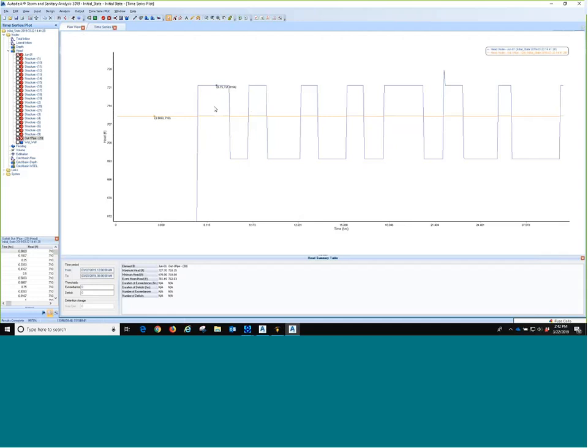So I'm going to use this information and say, hey, just so the thing dribbles out of the end, I need that many feet of head for my pump, and I can use this actually as my pump selection. Oh, I might even use this peak over there, but that might be more of a non-dampening inertial term that I forgot to set. So I'm guessing it's more likely here.